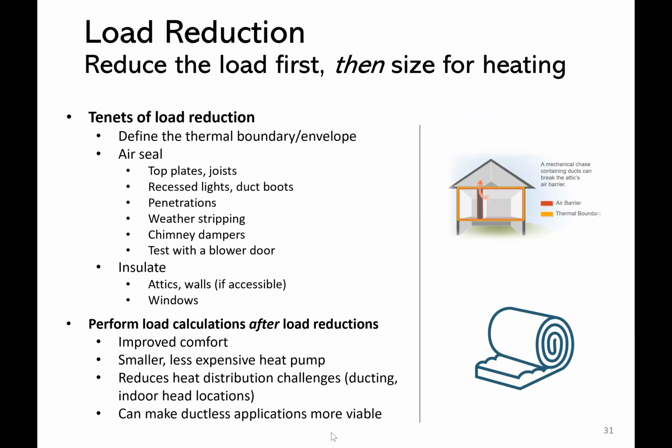This can allow for smaller and less expensive heat pumps and ensure the system is not oversized for the home's actual need. This will also make it easier to match available heat pumps to the home's overall load and energy need across all conditions. A leaky, high-load house requires a larger heat pump to cover the peak heating need, which inevitably leads to an oversized heat pump for mild conditions.